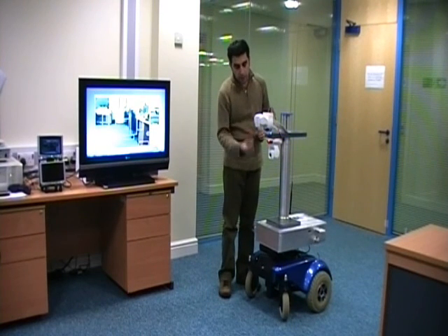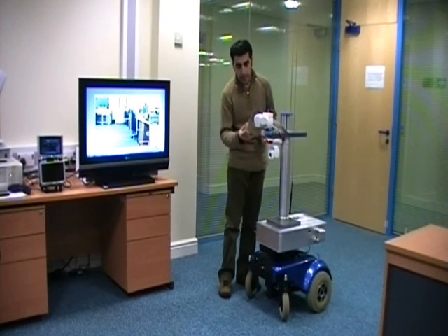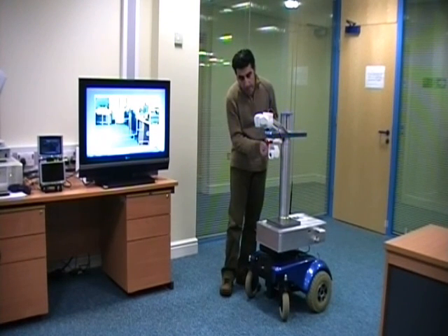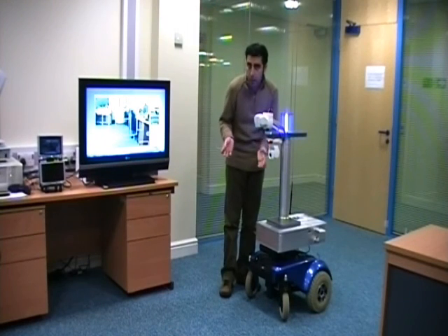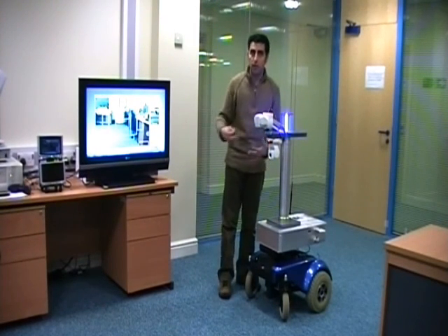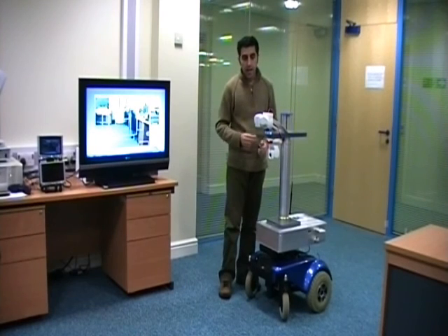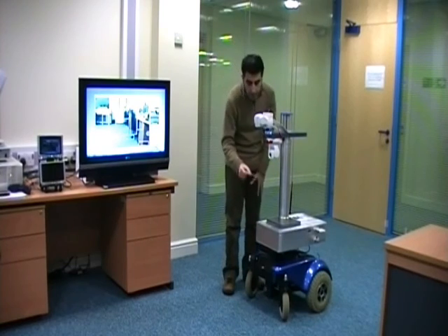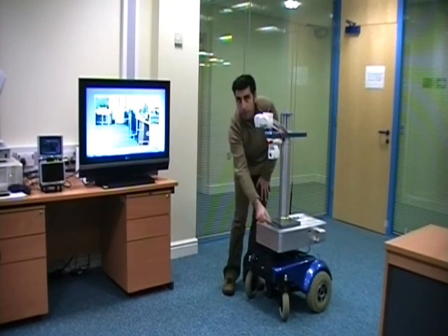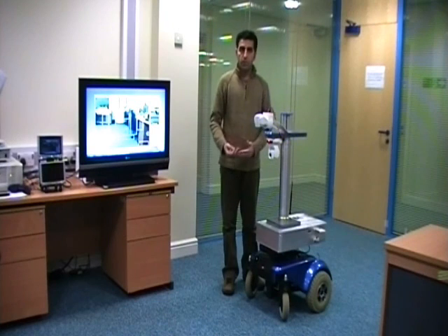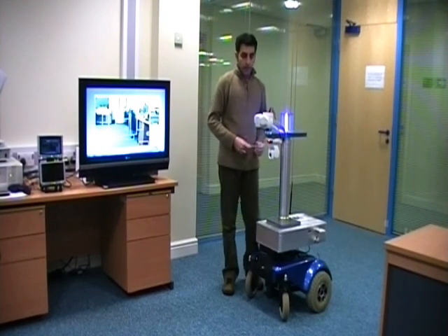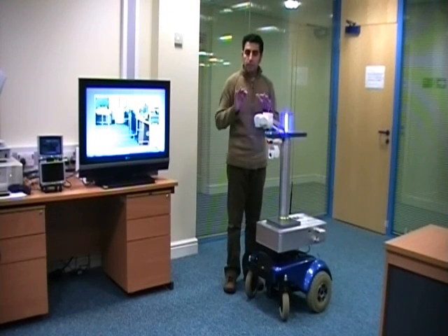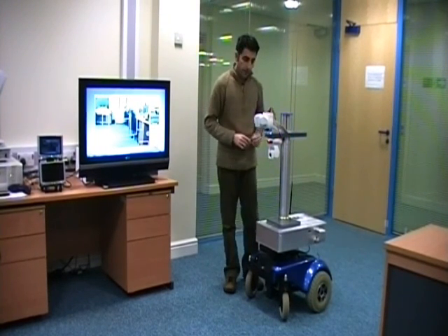You can see we have two cameras here, two mounted cameras, and they are both pan-tilt cameras. One camera is mounted such that it gives the operator a wide view or a main view to the surrounding. Another camera is mounted downward such that it gives the operator a very close view of the surrounding of the robot in order to avoid hitting some objects or obstacles in the way. Now that means we have two views that need to be positioned or displayed on the interface.